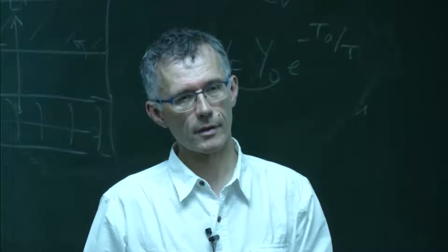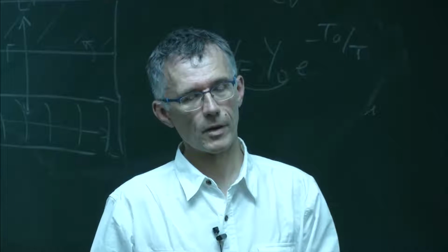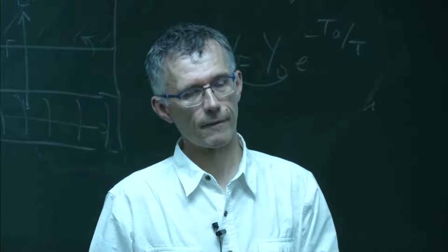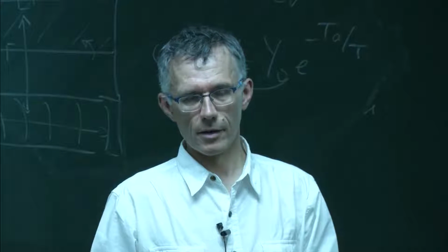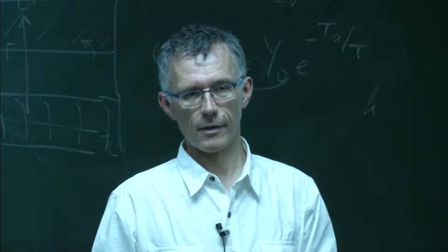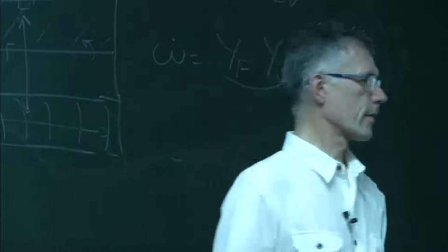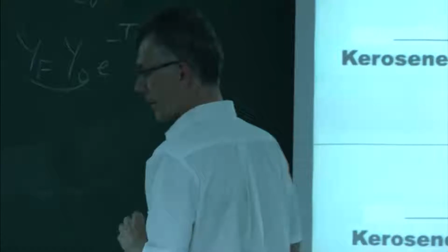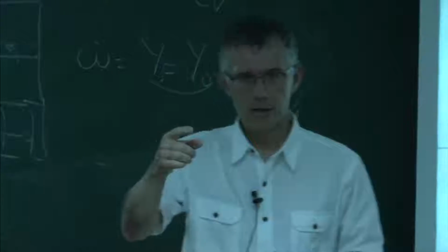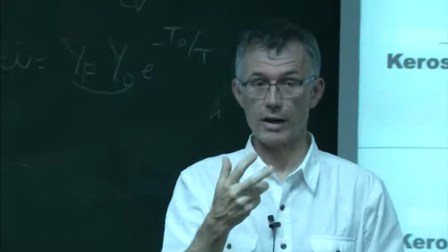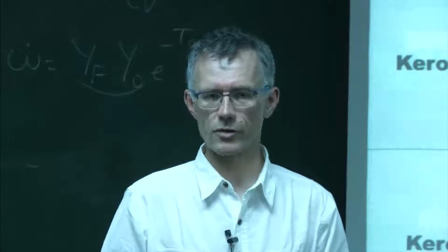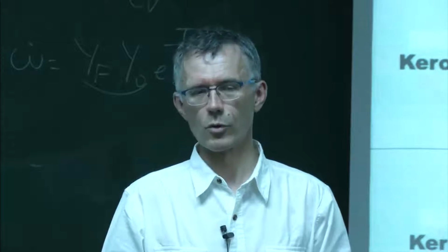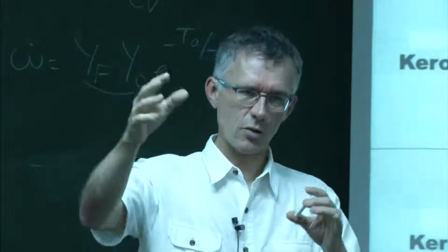In the previous condition, we saw the bluish region burning out. Is that because of CH radical, because the bluish flame appears? So is that bluish flame post-flame region or the flame front region itself? Can you repeat that? In the previous condition, we generally see a bluish region of flame. So is that bluish region post-flame condition or is it the flame front? The blue radicals you see are after the flame front, okay? And those are the radicals that you see with your eyes, okay? In the blue zone, I'm not sure which radicals you see exactly, probably OH or something like this. CH is very limited. OH is much wider behind the flame.